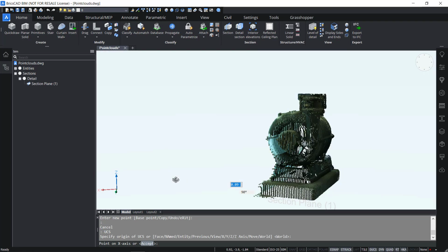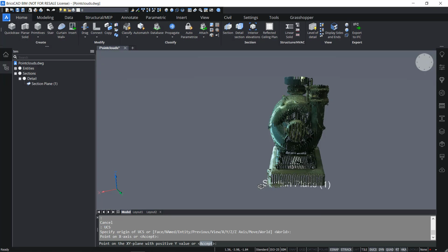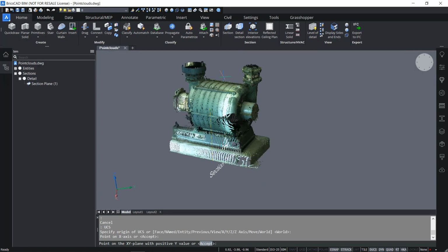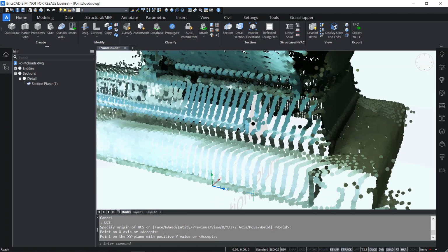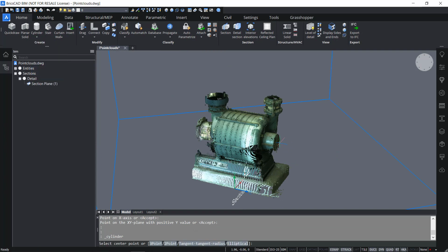And then to the other end, I want as well my section box, so the x-axis along my section plane, and the y-axis I want to point where now I have my z-axis. So I point it upwards by holding down Shift in ortho mode. And then you see it's oriented like this. So if I now start to draw a primitive, a cylinder, I will start to draw in this plane, because it's in the XY plane that I'm now drawing.